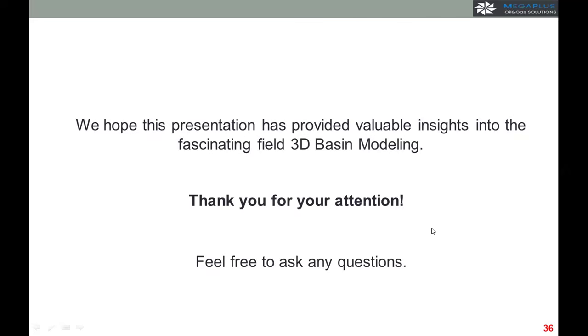The main benefits of Petrel that are not present in PetroMod are more equations and more interpretation. This is my opinion, from my experience on the fields I work on. I prefer Petrel because you can use all the PetroMod workflow in it. Also, the main issue with PetroMod is that you can use lithology as an interpretation, as a facies, but you cannot distribute these facies in PetroMod.